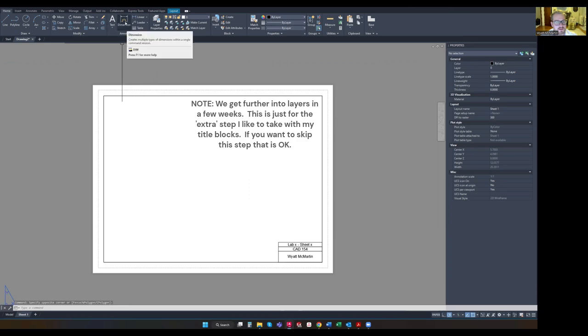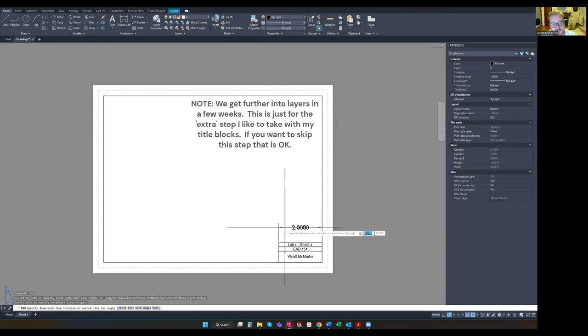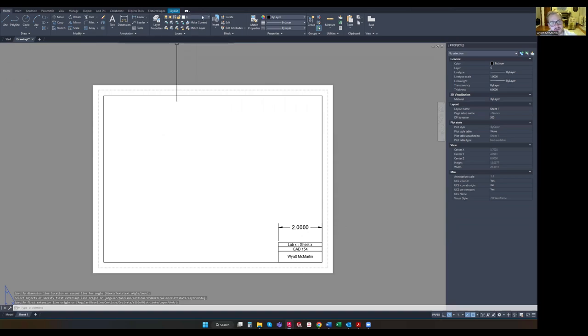So if you click dimensions, so like everything we're drawing, we're not talking about layers right now. We're going to put something on another layer that happens automatically. So I'm just explaining this. Everything we're drawing is on this 0 layer, which is where we want it to be. There is another layer that happens automatically when you enter a dimension. So if I click this dimension button and I just dimension anything, click escape to get out of the dimension tool. Now, when I come up here, there's this other layer called def points.